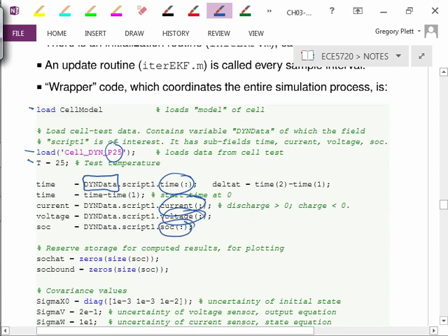Now, this is not something that we measure. This is something that in the lab test was calibrated, as we mentioned earlier in this chapter, by having a defined charge to 100%, and then I run my test script, whatever that is, to its end, and then I do a defined discharge down to 0% afterwards. So this point is calibrated, that point is calibrated, and I very carefully measure ampere hours in the middle, and that allows me to do Coulomb counting to get a state of charge estimate that, because it's highly calibrated, is a reasonable estimate of what the true state of charge is.